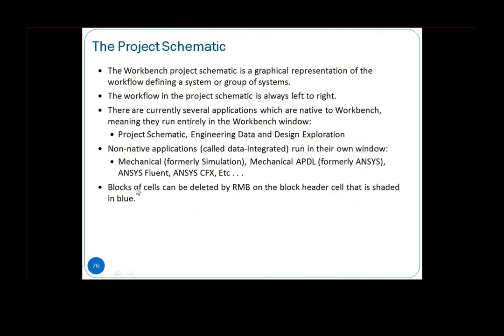Then the project schematics pane, or what we call the section, is basically a graphical representation of your workflow. Basically, it's more towards the analysis that you are doing, and it comes with a flow, step by step, that you have to complete before you can move to here. So later on, I will show you in the graphical manner also. The workflow in a project schematic is always left to the right.